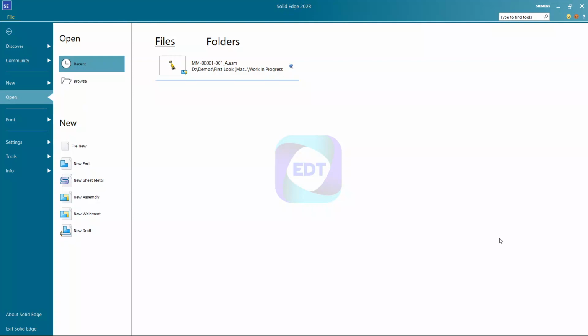So in this video, we are going to take a look at Solid Edge Mold Tooling and the various functionalities which are available within the Solid Edge Mold Tooling application. To start working on Solid Edge Mold Tooling, we have to start with the blank assembly, define our project, and then set up the component with the parting lines and the surfaces, and finally generate the mold base. So we will do all of that in this video.